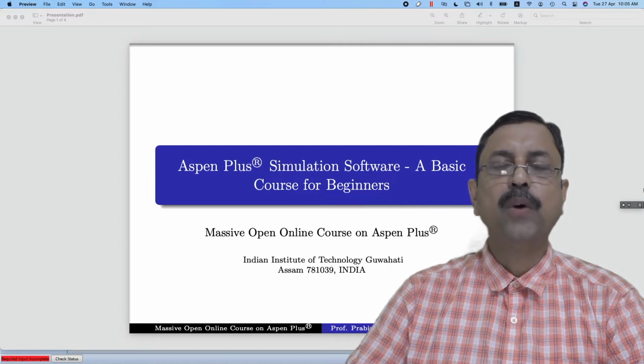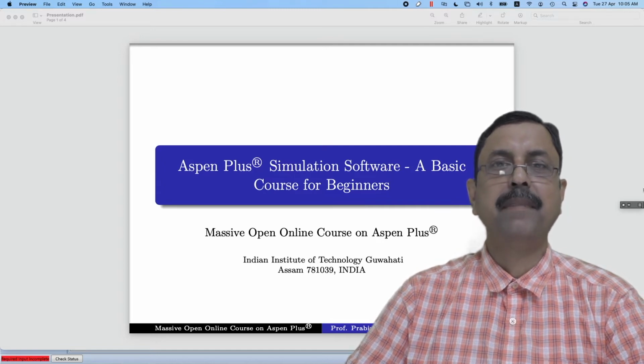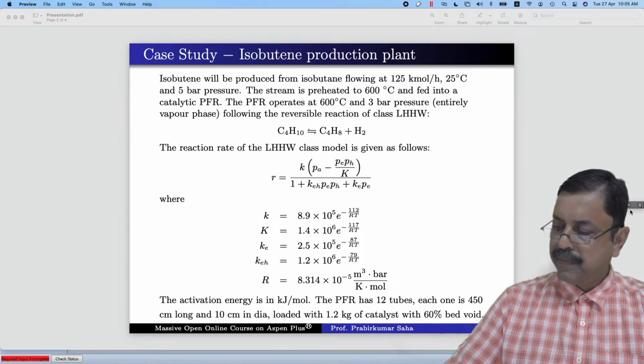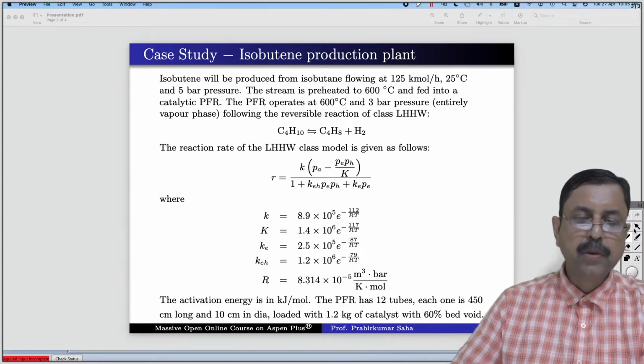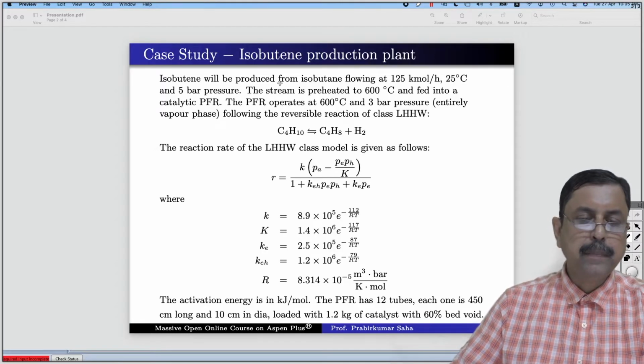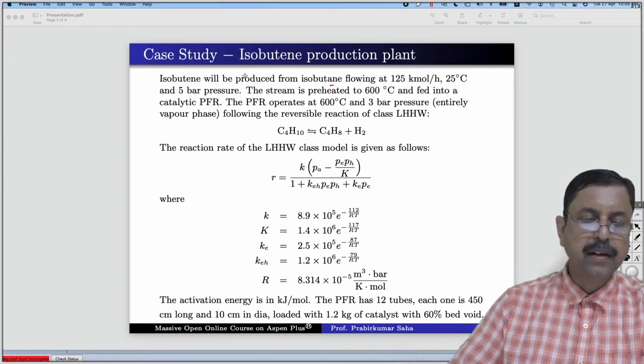Welcome to the massive open online course on Aspen Plus. In today's lecture, we shall perform a case study on an isobutene production plant. The problem statement is something like this. The isobutene will be produced from isobutane flowing at 125 kilomole per hour, 25 degrees centigrade and 5 bar pressure.